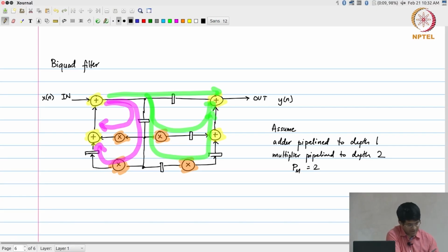So, now with this information in place, I am going to write down S1, which is for the adder, right. I am going to assume I have one adder and one multiplier, right, and before I can write S, I also need to know what value of n to use. What's a suitable value of n? How many phases do I need? 4. Why 4? Because there are 4 adders. So, with one piece of hardware, I could do it in 4 clock cycles. How exactly, I do not know yet, but that is the bare minimum, that much I can be sure of.